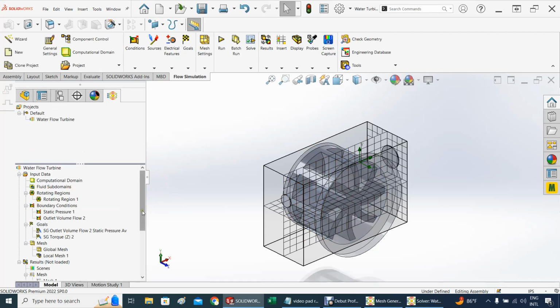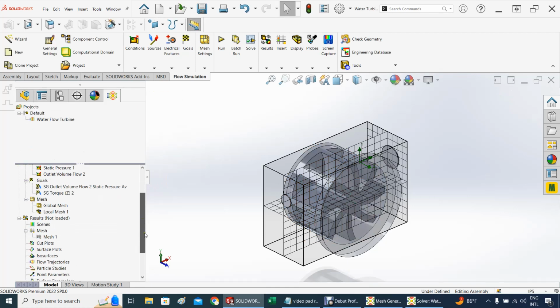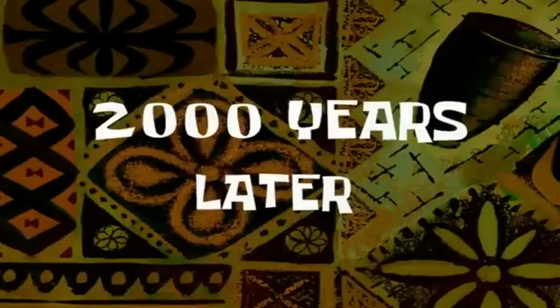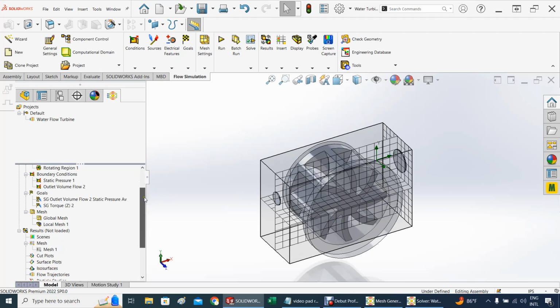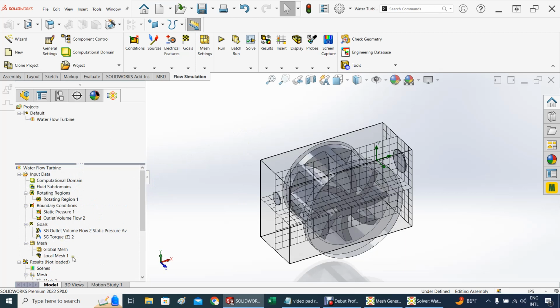All right, so I know there's something wrong, and it's funny. My eyesight is not good, but here's the problem. The outflow, 1.5 gallons per second. That's huge. That's humongous. And that was the problem. It's 1.5 gallons per minute. So the unit, I picked the wrong unit.